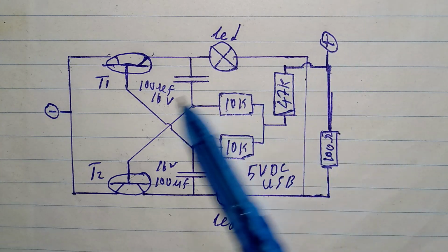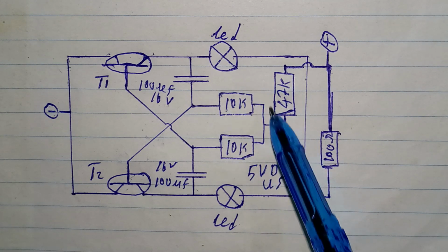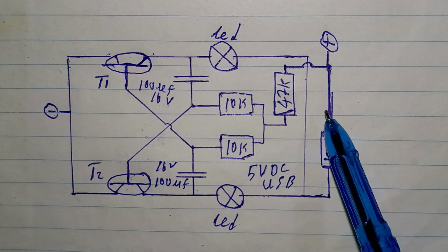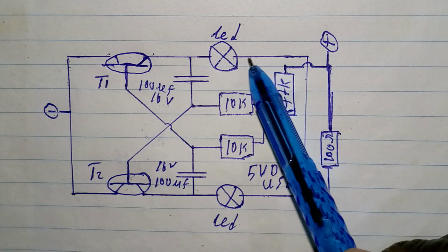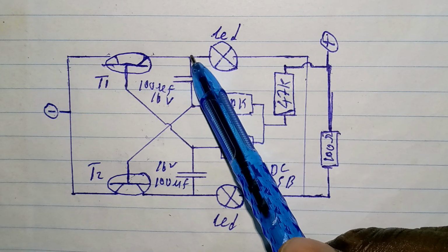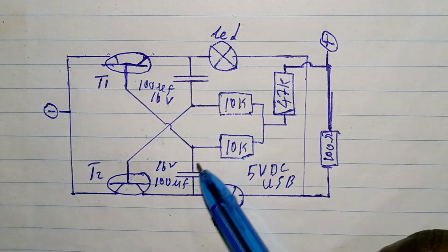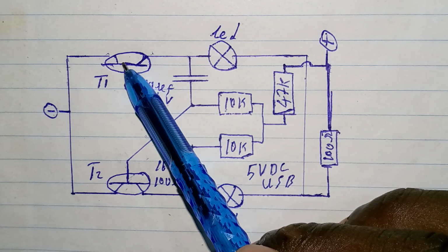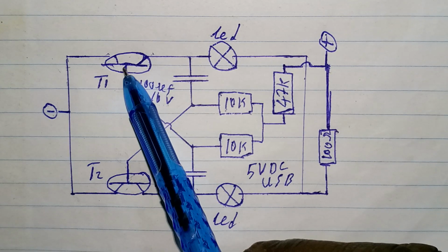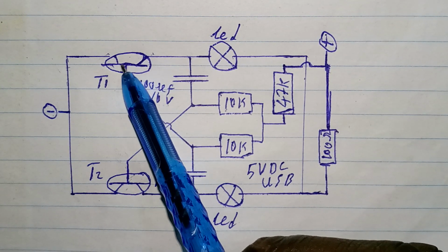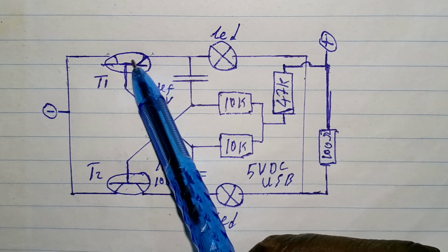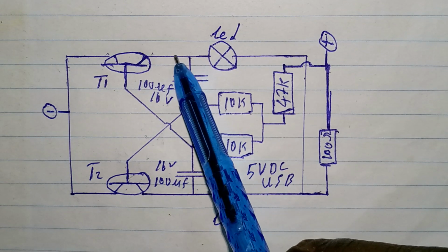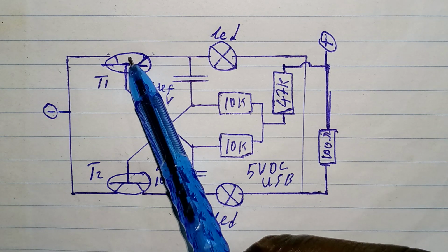Now, when you power the whole circuit here using 5-volt DC, the voltage is coming into this point. If this voltage is being applied to T1 here, T1 resistance will be decreased, and then a voltage is now going this way. Therefore, the resistance here is now decreased.